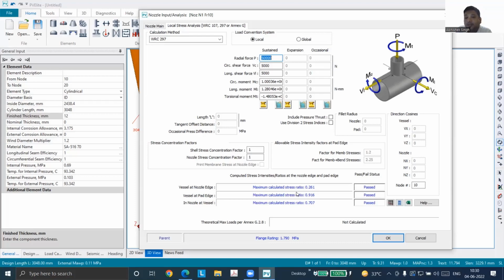So if something hits your nozzle, maybe during transportation or installation, it may immediately break. It will be very weak. So just to strengthen the smaller 2-inch nozzles, which are very fragile, we provide stiffeners. Two stiffeners, 90 degrees apart. That is the standard.